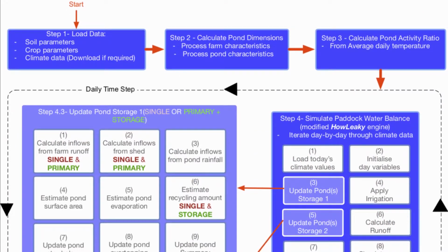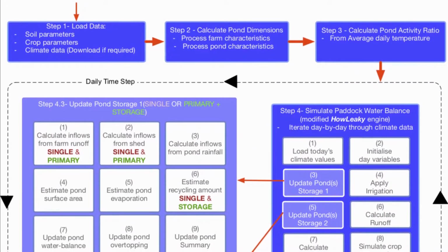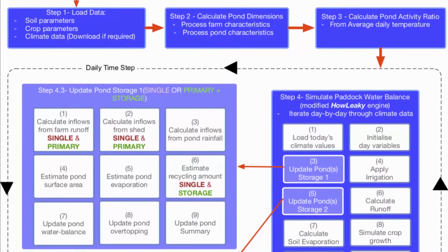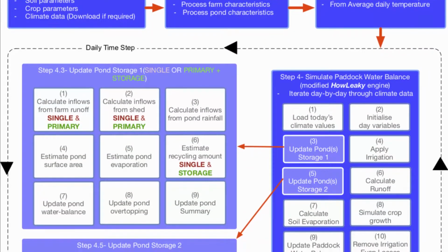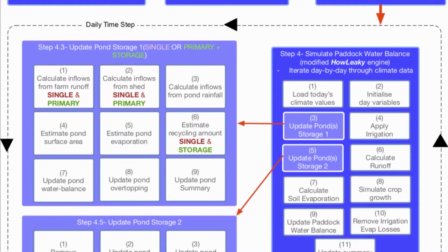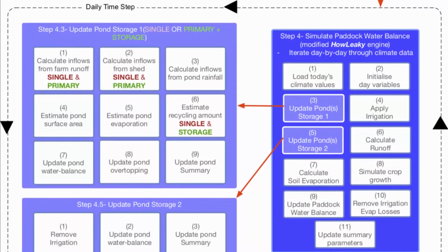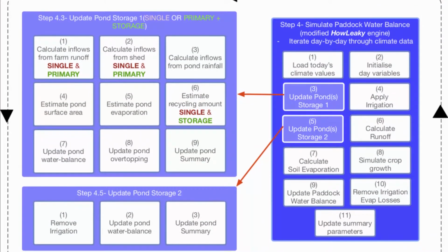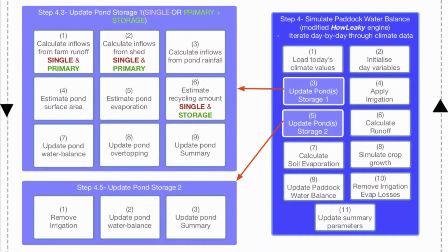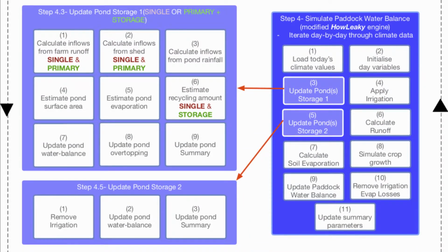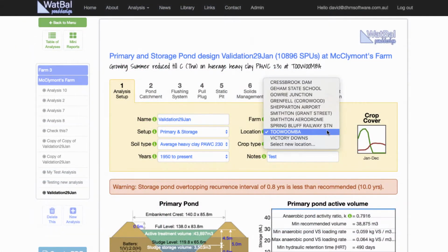A daily water balance for the soil in the effluent application area is used to trigger effluent application to the land when soil water deficit reaches a selected value. The user can select an appropriate crop or pasture species and soil type for the effluent irrigation area. Data for a range of typical crops, pastures and soils are included in the model.